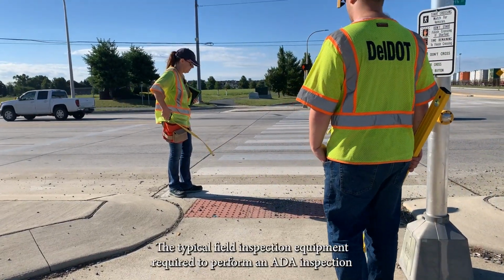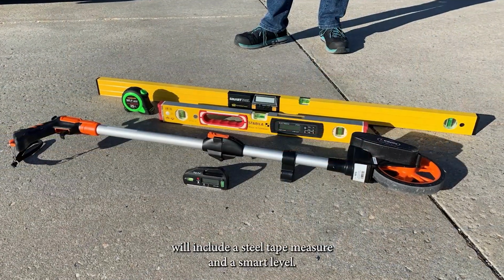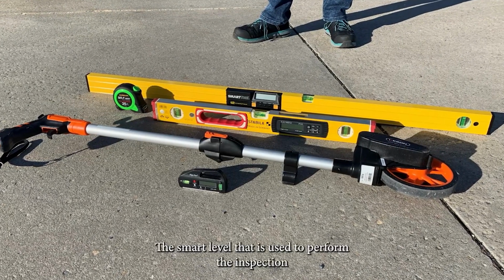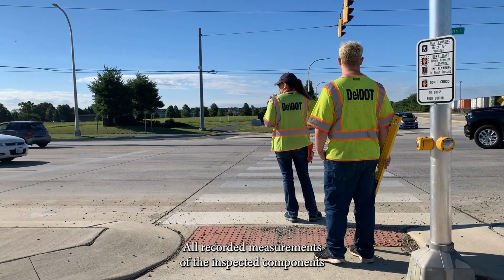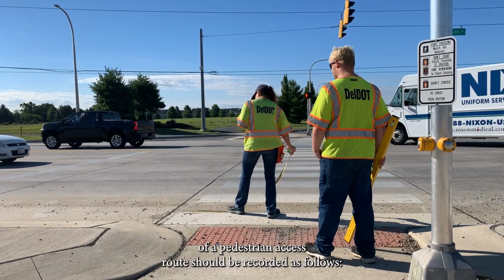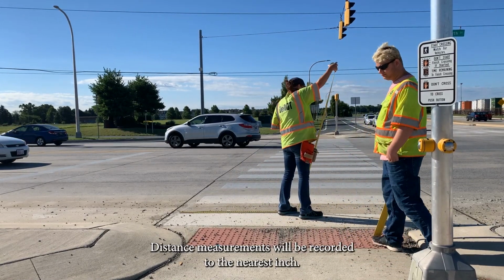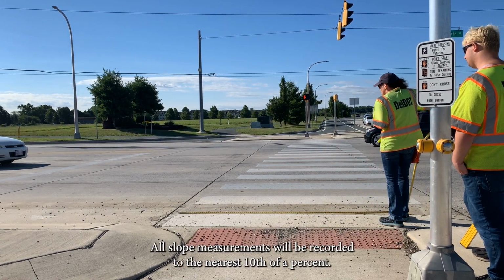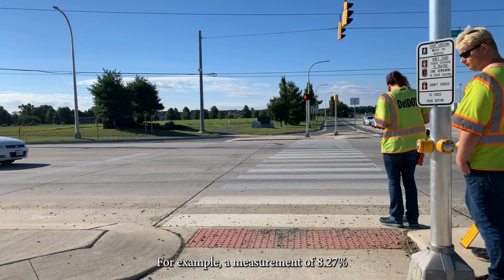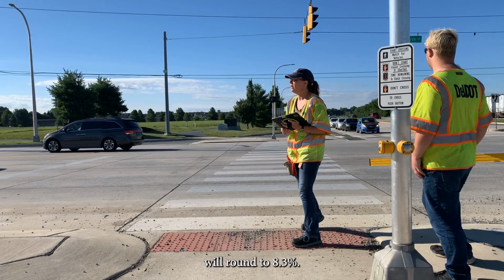The typical field inspection equipment required to perform an ADA inspection will include a steel tape measure and a smart level. The smart level that is used to perform the inspection shall follow the calibration requirements of the manufacturer. All recorded measurements of the inspected components of a pedestrian access route should be recorded as follows. Distance measurements will be recorded to the nearest inch. All slope measurements will be recorded to the nearest 0.1%. For example, a measurement of 8.27% will round to 8.3%.